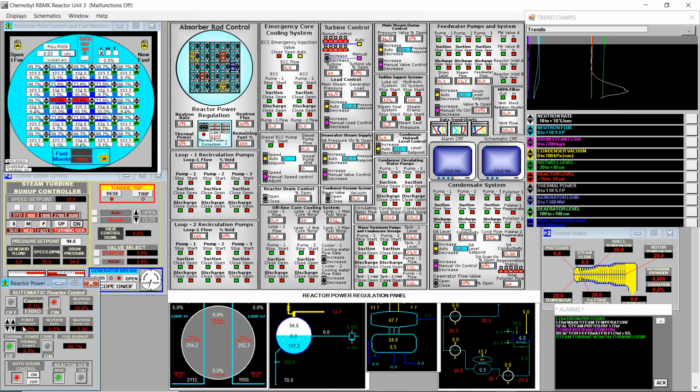Okay, and because the drum water is already boiling, I will increase the reactor power a bit further. But do not go above 15% because some systems need to be adapted for a power higher than 50%. Like the feedwater pumps need to have a second pump connected, also loop 1 and loop 2 and several other things. So let's go to exactly 50 to speed up the process.